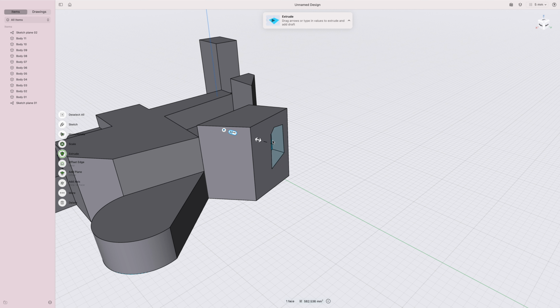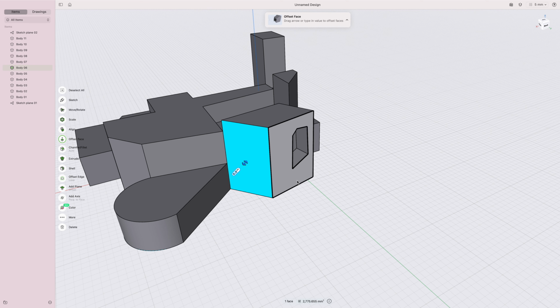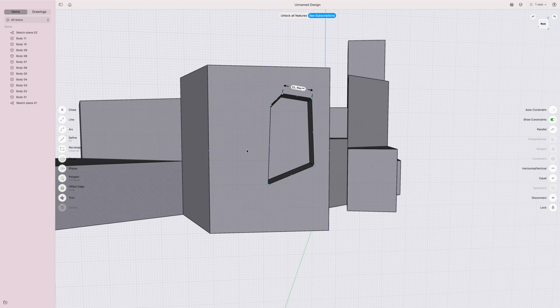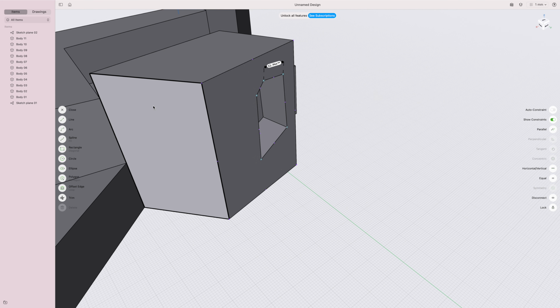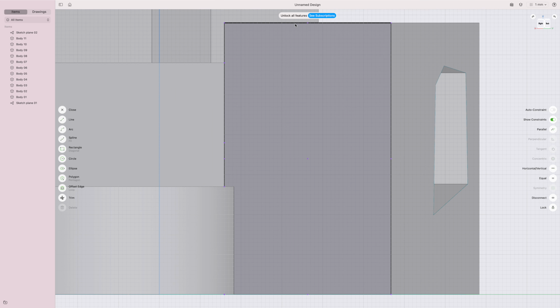Okay, and then you can do something that's pretty much like BoxCutter, right? Let me do that again. Select this face, spacebar. Oh, actually, let me escape again. While this is hovering here, hit spacebar. Okay, now it's working.